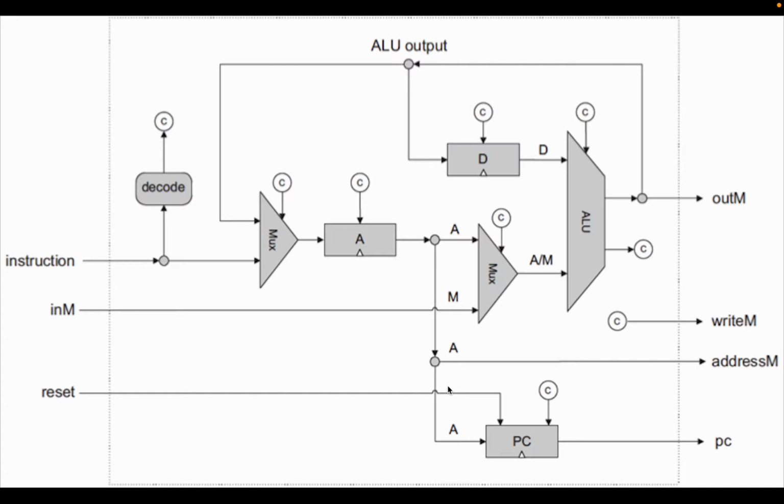The input pins consist of the 16-bit memory input inM and the 16-bit instruction that is used for the execution of the code, and the reset signal tells whether to restart the program. It also consists of the output pins, and here there is outM, writeM and addressM.